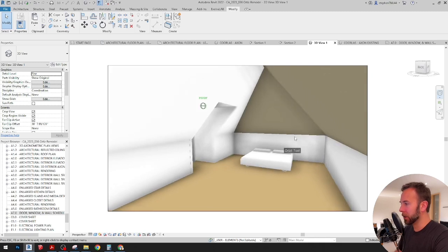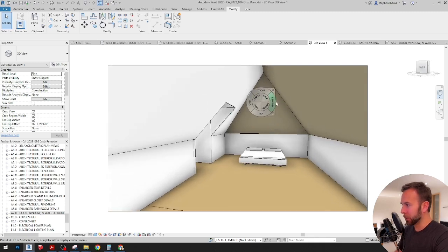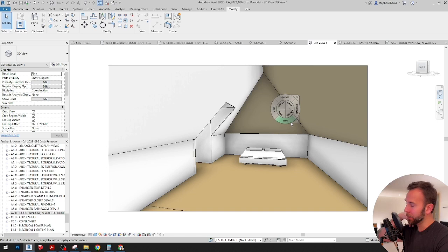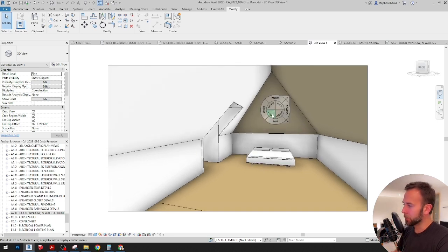So that's good. And then the rafter ties will come in. They need to be at the top 2/3 or top 1/3. So those will be cutting across the top there. We're going to have to put a ridge beam in across the roof to accommodate structurally, but we'll get to that later. But right now, I just want to make sure I'm getting these sort of